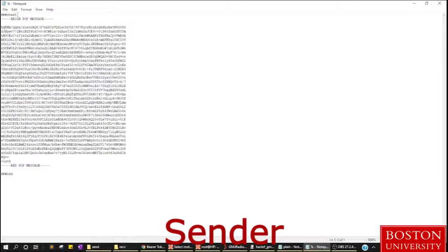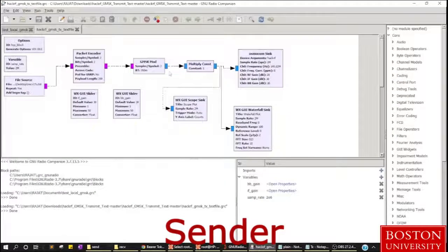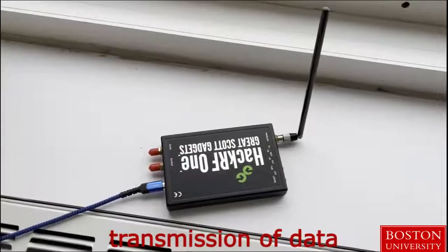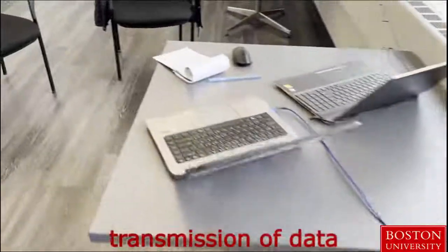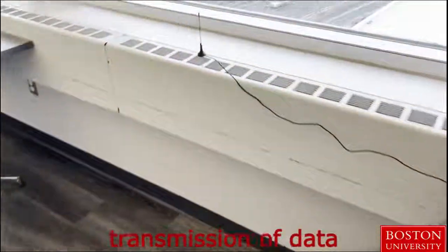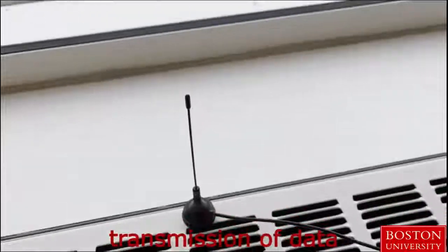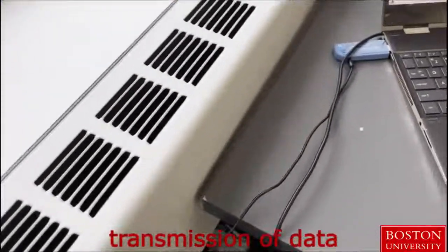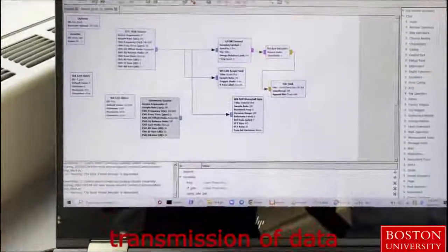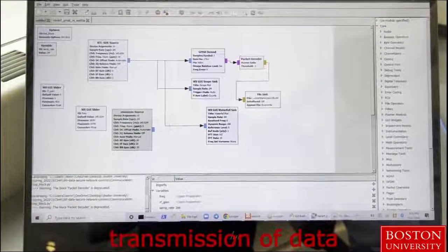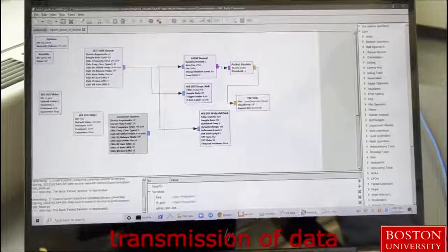GNU Radio will read this particular file to transmit, and for transmission we used GNU Radio as it is an open source software development toolkit that provides signal processing blocks to implement software radios. On the hardware side, we tested the system with HackRF and BladeRF micro, which is a wideband MIMO transceiver, and the receiver is RTL-SDR. It is USB powered, portable, and has a maximum sample rate of 10 megasamples. GNU Radio integration is provided via the gr-osmosdr block.